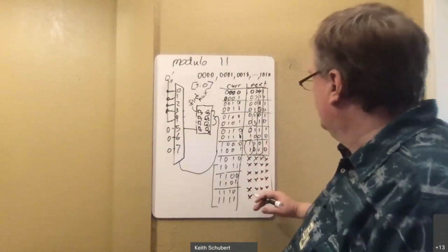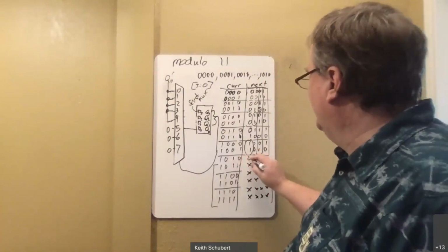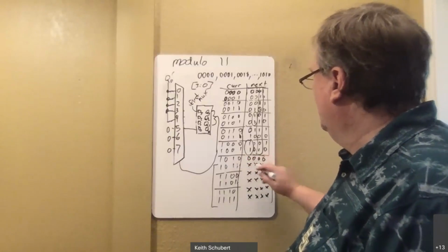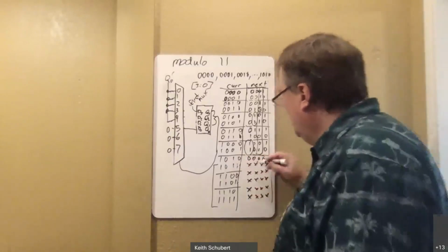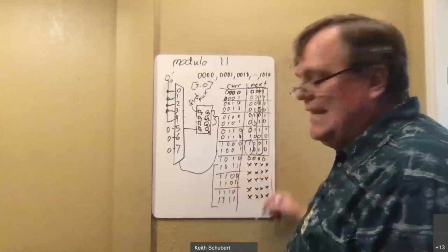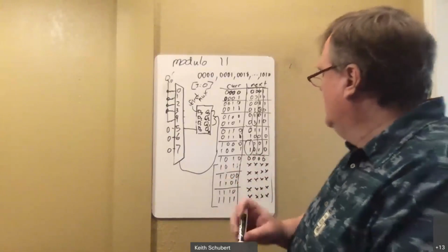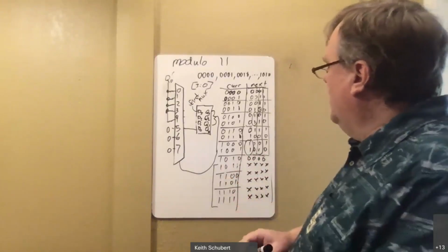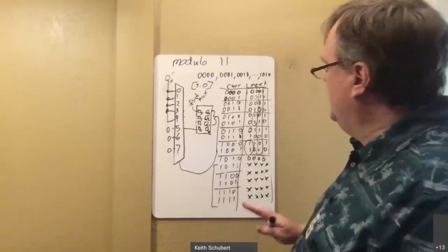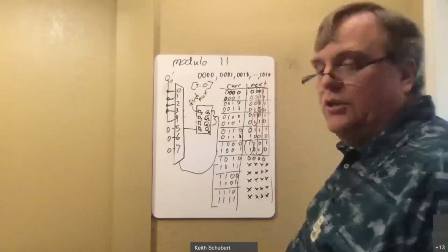This is the first thing. I'm sorry, 10 goes to 0. That doesn't change. That always has to go to 0. But the 11, 12, 13, 14, and 15, you have to make them X's. You can't do it without making them X's. And now you need to group these in a slightly different way so these X's get distributed around.